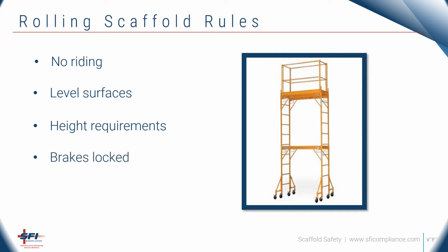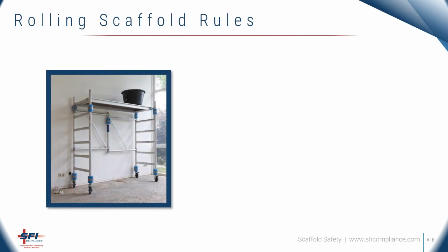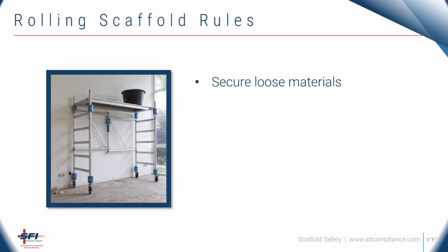Wheel brakes must be locked when the scaffold is not in motion. Get help when moving rolling scaffolds. Make sure that the route is clear and watch for holes and overhead obstructions. Secure or remove all loose materials and equipment before moving scaffold. Guardrails, mid-rails, and toe boards must be installed on all open sides of scaffolds 10 feet or more in height.